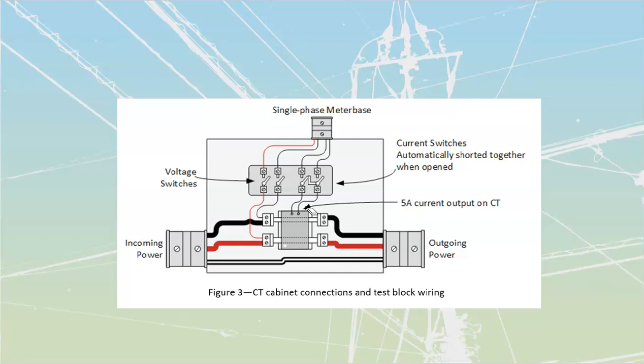There's always that danger with the CTs, and we've talked about this before, that anytime you're going to remove a CT, you should be shorting out that meter first. The test block is going to allow for that.